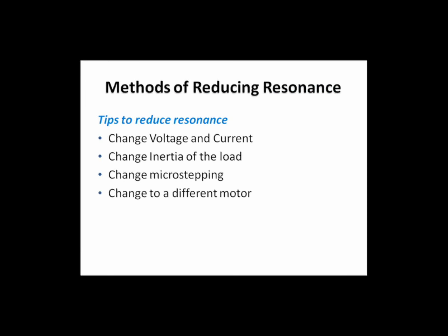And if none of those work, it could be that you need a different motor. In most cases, we've seen users choose a motor that is too much power for the job. Some people worry about not having enough torque, and they oversize the motor, and this could actually cause more resonance, and it could be that you need a smaller motor.